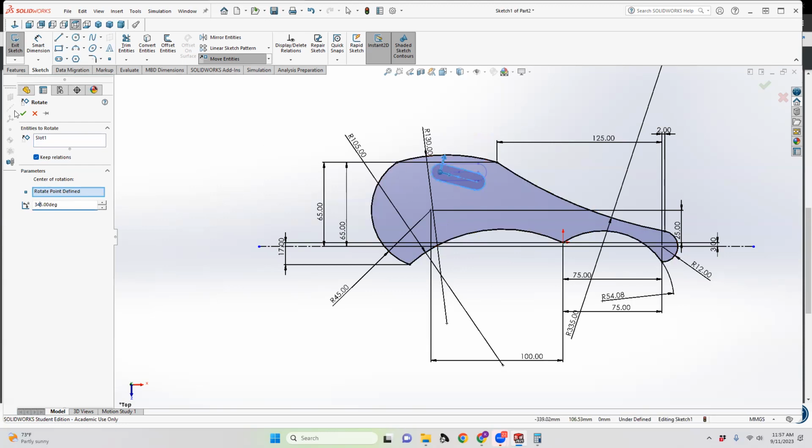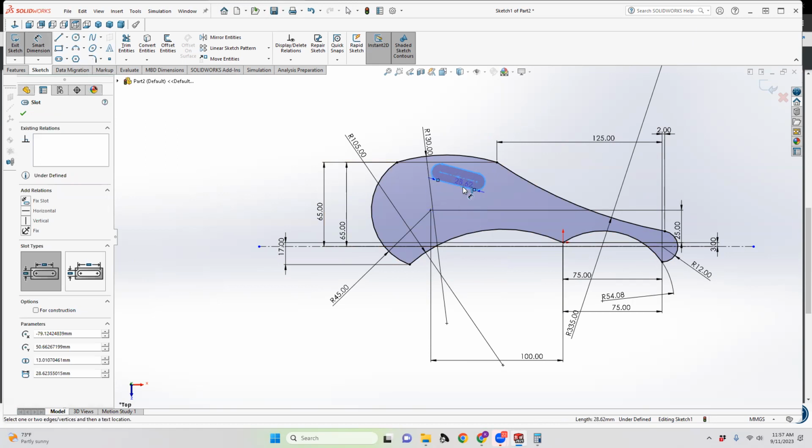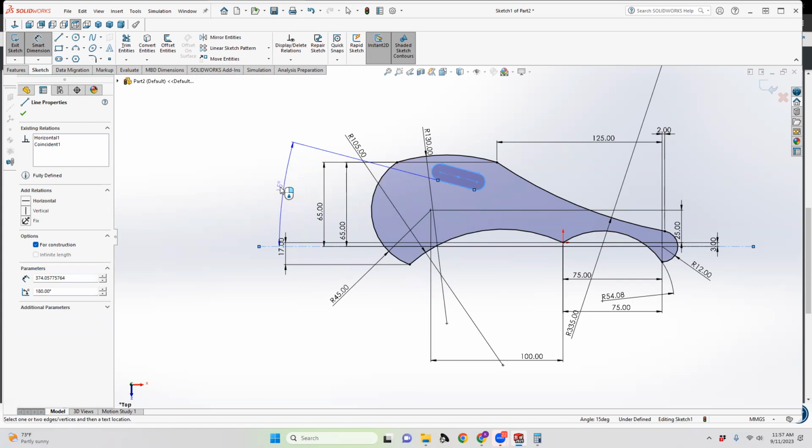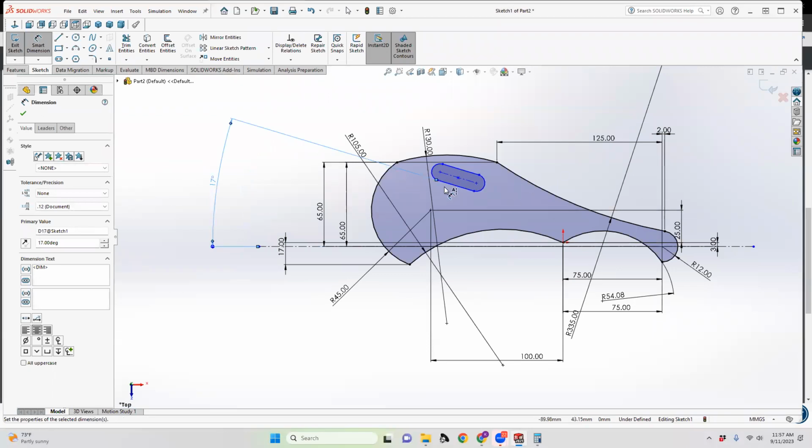Once we've got this rotated, you can actually see an angle measurement by grabbing one line and then a center line. Now it tells you the number of degrees of separation. You have to click not on the center line or on the center point, but somewhere on the actual line itself. And you can say, okay, actually, this needs to be 17 degrees, and it'll make adjustments.